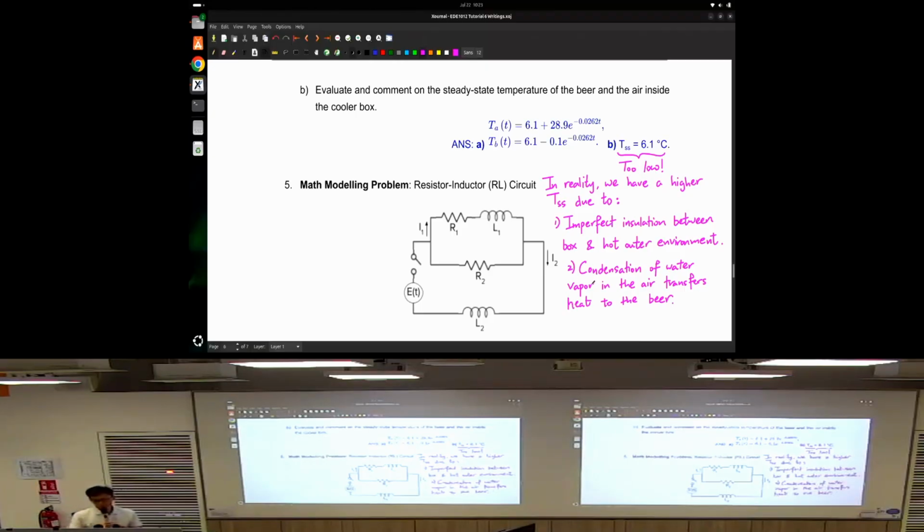Okay, good point. The thing is, heat capacity stays quite constant. There will be changes, lah, dependent on the humidity of the air. If the humidity changes, then the heat capacity changes as well. But it remains roughly constant, unless your humidity or your pressure changes a lot, then the heat capacity will change a lot. But this one I think is negligible, lah. The change in the heat capacity is typically not modeled that accurately unless your temperature change or pressure change is very huge. Okay, yeah. So predominantly, I think it's the condensation effect.